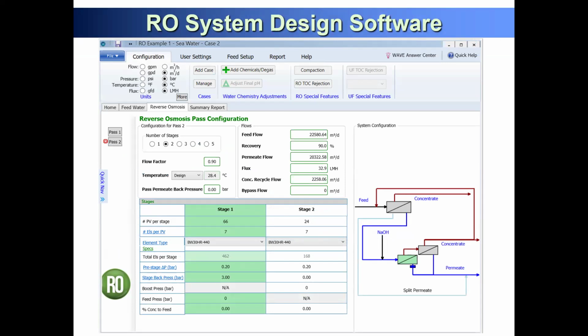So this is the reverse osmosis system design. You can see you have several back pressures here, the permeate split, and this is your first stage, and this is the second pass. So you can also have a diagram for your membrane RO system design. In your assignment, you design your membrane second stage and second pass, and try to show this diagram.